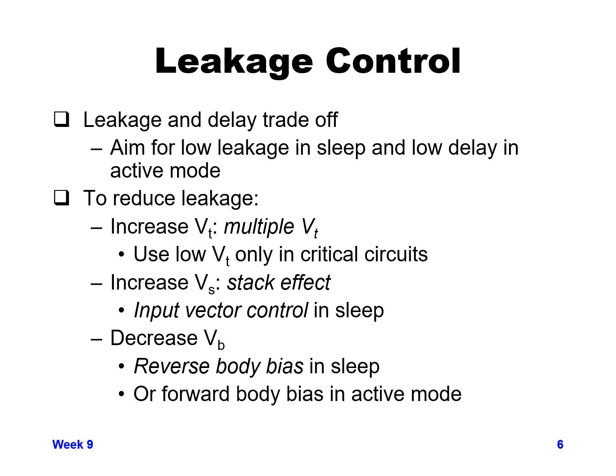When you know you're not using that logic, you can turn that transistor off, have it off in series with all of your normal logic, and wind up getting a really large decrease in your static leakage.